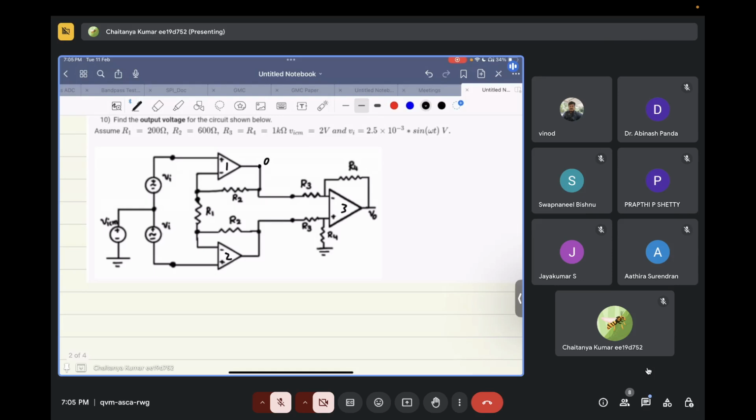What can you say about op amp two? So also negative feedback. Yeah, again, through R2 there is a negative feedback, and in op-amp 3 through R4 there is a negative feedback. So that means to say all the op-amps have virtual ground in them. Now, mind it how the signal has been given to this complete circuit. So this is a differential way of giving the signal.